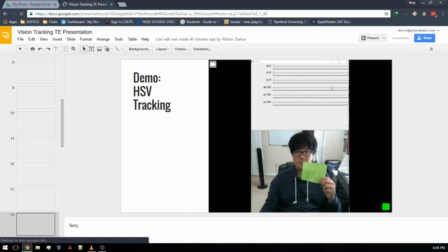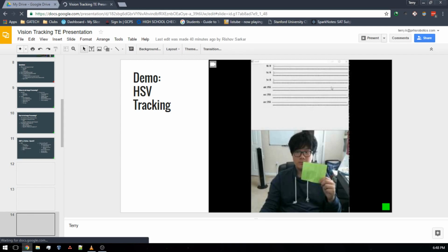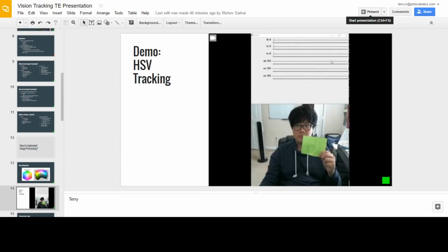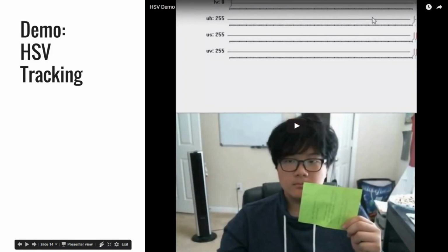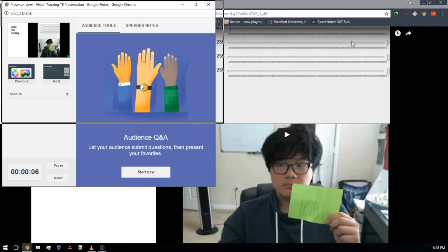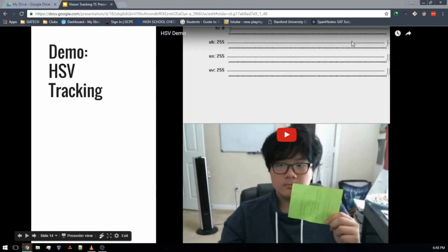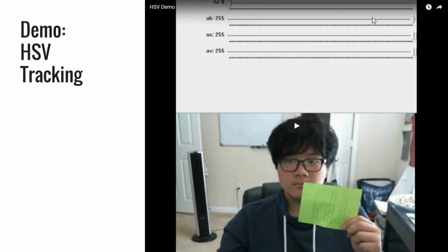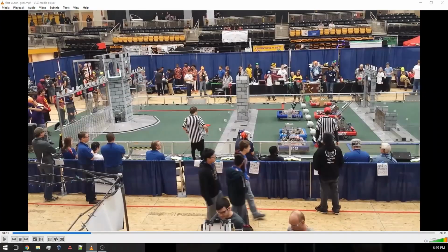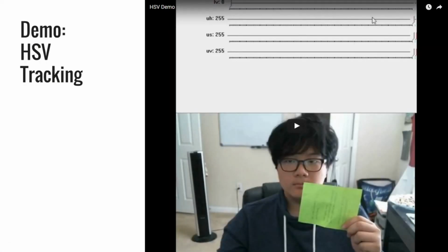Okay, while we work this out, I'm going to answer a few questions from online. Somebody is asking if the Raspberry Pi 3 would work well with the RoboRio. In our experience, yes. We can't give any advice on GRIP because, as we said, we chose not to use it, since when we used it, it was not supported very well on Raspberry Pi. But we personally use the Raspberry Pi 2 and PyNetworkTables to run our code alongside our RoboRio. PyNetworkTables is basically a Python compatible version of NetworkTables. It allows you to communicate back and forth between the two. So your Raspberry Pi 3 should work out just as well. You just have to have the correct version of PyNetworkTables to go with it.